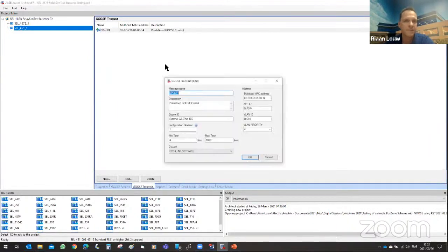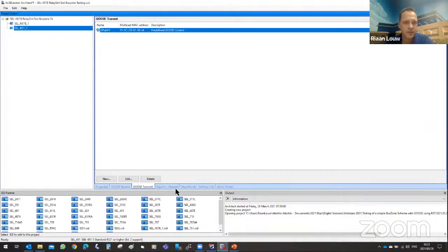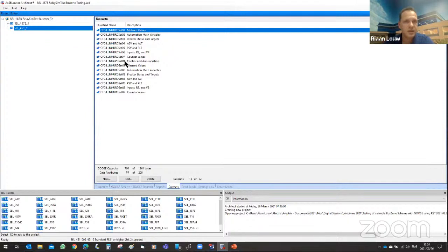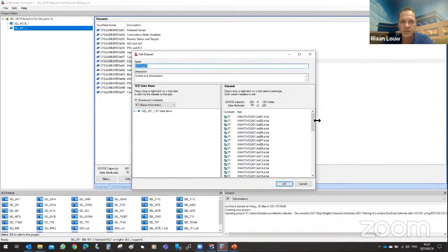I'm sending data set GPD01. So we can go to our data set here. It's this one over here. So here are all the signals that I've configured. For those familiar with 61850, I could have used the 61850 double bits for breakers and disconnectors, and stuck strictly to the 61850 standard, but I've gone for the GGIO simply because as a protection guy, I like to associate input 101 with virtual bit 001.